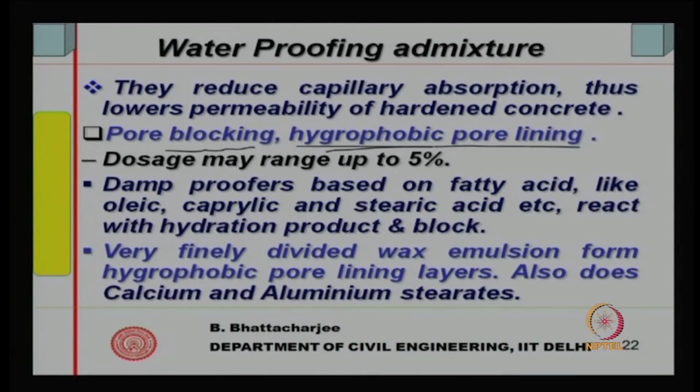Now, what should this do? When they are coated onto the capillary surface, the contact angle of water has changed. So, the ingress of water by capillary suction becomes difficult, because like mercury, which you cannot just push into any pore or capillary on its own, you have to force it.